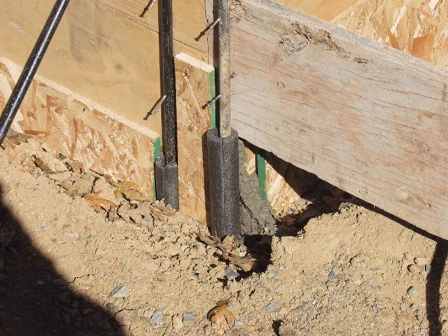What we've realized over the years is that if we wrap a little plumbing pipe insulation around each of our concrete stakes, when the concrete does squish out from the holes that it will inevitably find, it wraps itself around the insulation and not around the concrete stake. So when we're ready to strip our forms, we can pull our concrete stakes straight out and they don't have any concrete holding them in place at all. It's a cheap and easy fix to a very frustrating problem.